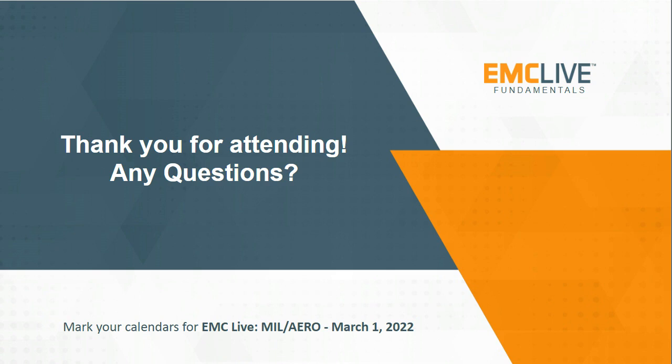Next question. Should I use a power meter in watts or in dB milliwatts? I always prefer to keep everything in dB and not convert to the linear term unless you absolutely 100% have to. The reason for that is, as you can see in some of the calculations that I showed during the presentation, it's not exactly 107, it's not exactly 34, it's 106.99, it's 33.97. If you start converting between dB and linear, or logarithmic and linear, you run the risk of rounding errors factoring into your resulting measurement.